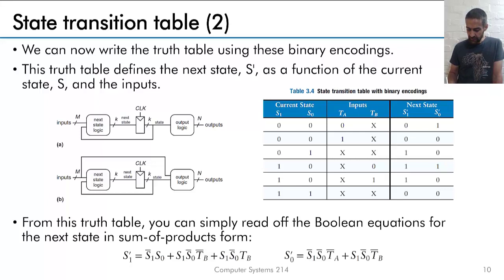So just look at this. If you just consider S'1, or the next state most significant bit, this logic here must be 1 for those 3 ones. So we're just going to write it down in the table. Just looking at what changes here, this one is not S1, not S1, S0. So that describes this one.